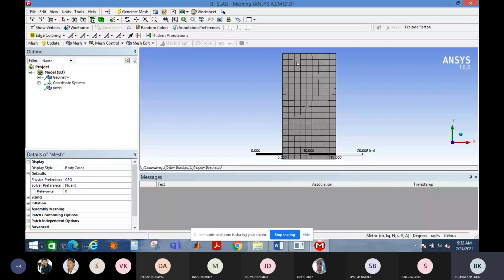Look, this is the horizontal length of the slab. If per length you have 10 blocks, then in Fluent those equations will be solved at these node points. So it means we have 10 points, and Fluent will solve at these node points. So the space, these lengths of the slab, will not be considered in Fluent.